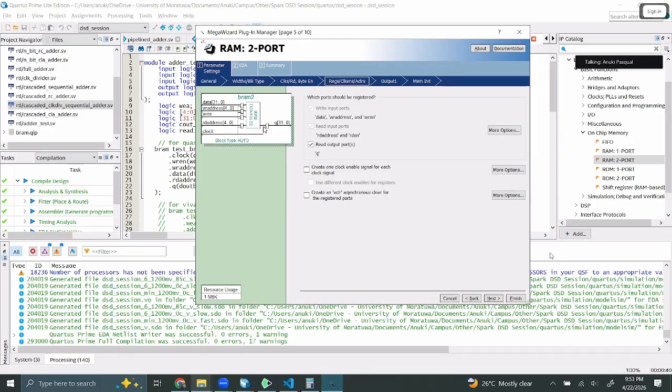So this is asking whether we need an additional output register. It shows this clearly. There is already a small register, a flip-flop, at the input. If you keep it like this, there will be only one cycle delay before the output. If we add two registers, then there will be two cycles of delay before we get the read out.